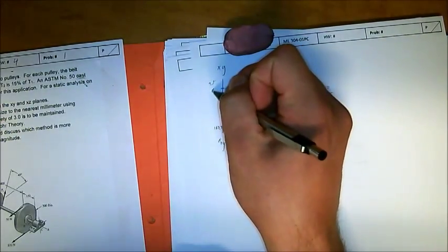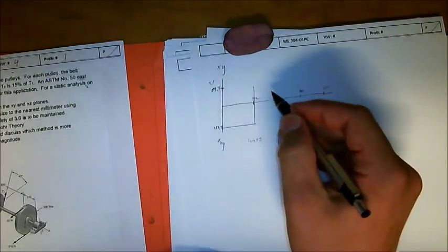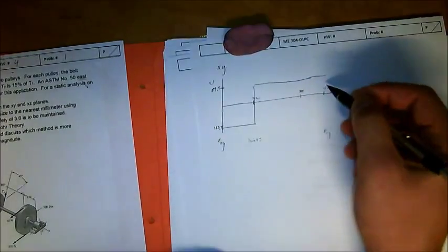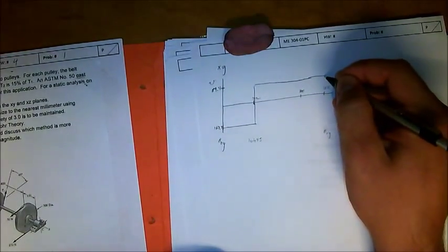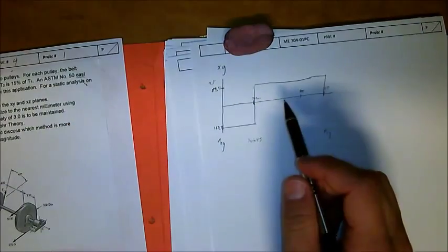Like that. And then you know that's going to be constant all the way along there until we get to shear, and then we know that RCY is equal to negative 89.4. So you know that your shear diagram goes to 0, so you know that works. You did your sum of the forces right, and it makes a nice pretty diagram.